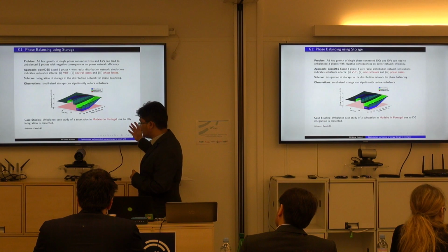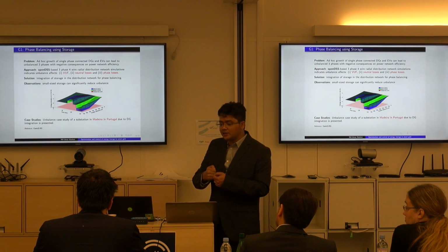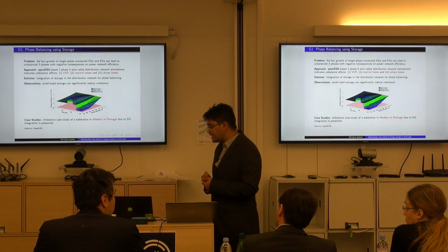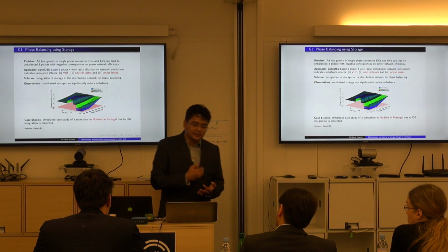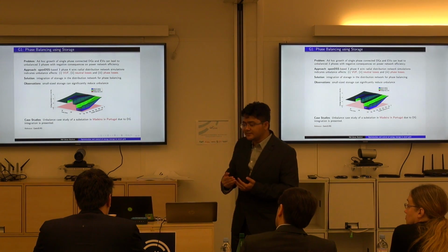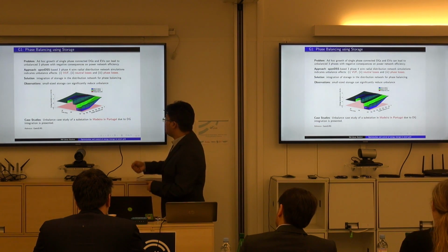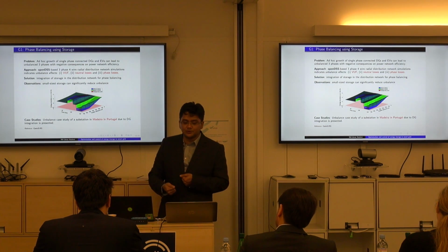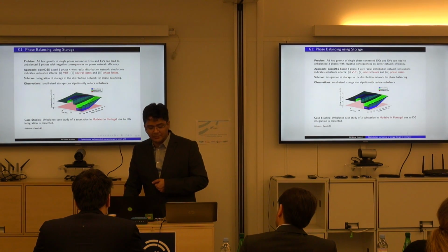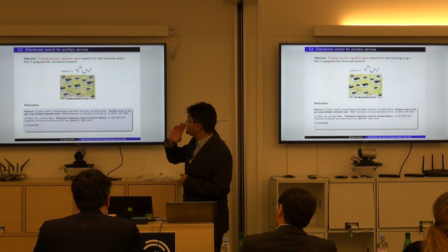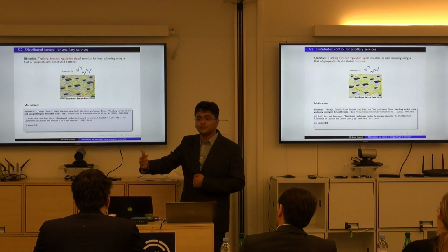And then we present a case study for a substation in Madeira. We collected data over longer time scales. During the day, we observed that whenever the solar generation was there, the imbalance was increasing, because most of these DGs were connected to one of the phases. So we think that if there is in future an ad hoc growth of renewables, it can create significant imbalance. The second application is tracking of a regulation signal, which is providing an ancillary service to the utility.